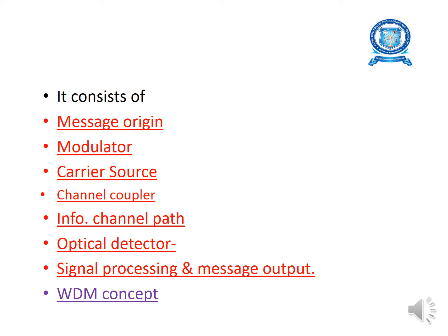The amplifier receives the electrical signal from the optical receiver, amplifies it and sends it to an optical transmitter. The optical transmitter converts the electrical signal back to an optical signal to send down the optical fiber waveguide. These are all the processes which take place in the repeater unit.